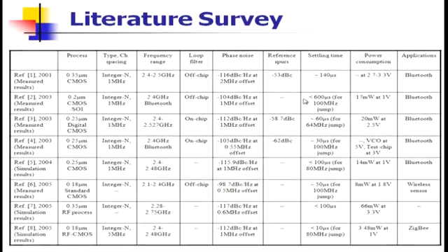And the settling time. Settling time is an important issue because the frequency synthesizer is synthesizing from the lowest end of your frequency to the highest end and again going back. So now suppose you are transmitting to me on channel 1, then channel 2 and so on, up to channel 100.